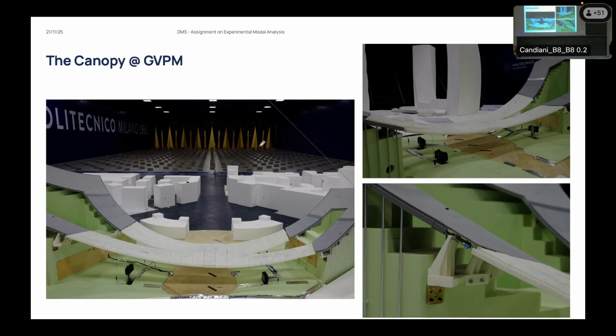And so those columns cannot serve structural purposes. What they are used for is to embed some dampers to damp out the vibration of the system, but also to remove water that could otherwise be stored on the roof. When it is raining, due to the shape of the coverings, some water is going to be stored there. To facilitate the water flowing away, they made some paths over the roof, and then it will go downward through the columns you have there.